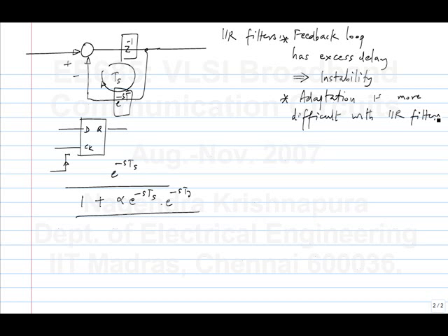Adaptation refers to varying the coefficients so that it matches the channel exactly. So the channel may be known in some cases, but may not be exactly known in other cases. You need adaptation. Adaptation is a way of automatically choosing the coefficients so that for an unknown channel you get the correct equalization. Okay. So firstly the channel may be unknown. Not that it's ever completely unknown. It's not totally arbitrary, but there is a huge range.